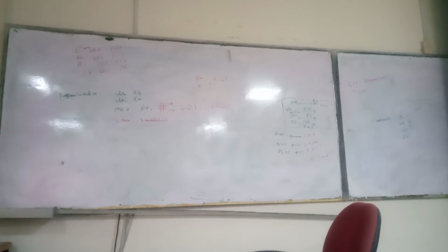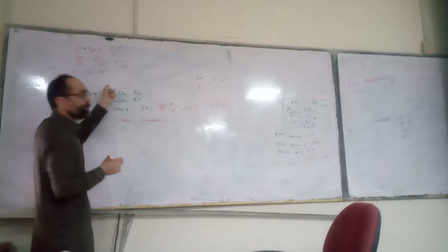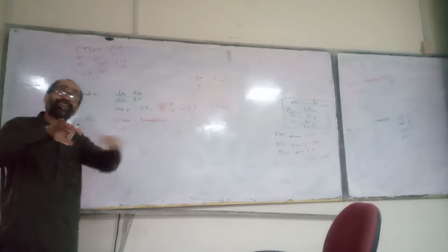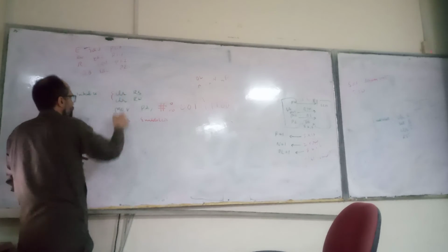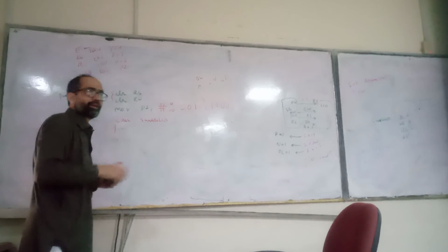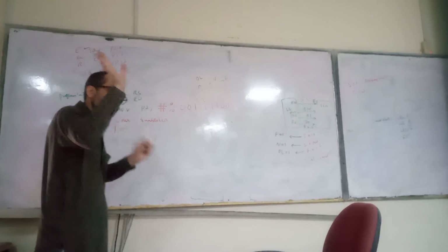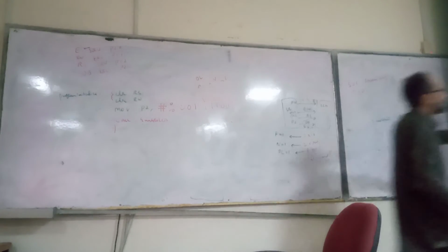Third one. So which data should we send now? Clear RS, clear RW. We don't need to change it because it's already done. RS and RW are already 0, 0. No problem. It's done. Clear RS and clear RW.